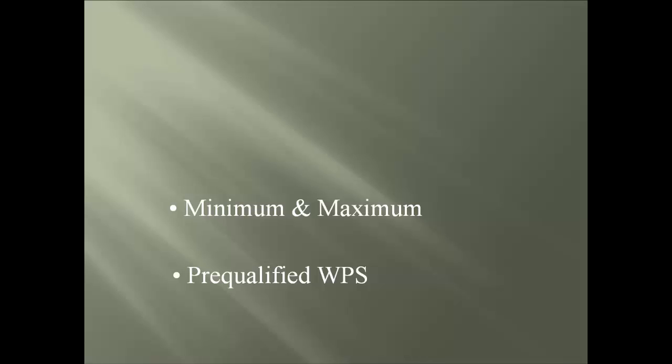Now, when the contractor does this, it's defined as exempt from a qualification test as long as the assembly is between sheet steel to sheet steel or sheet steel to a structural member equal or less than 3/16 inch in thickness. And if any deviation from the joint details approved by the AWS committee happens, this will have the proposed WPS needing engineer approval before production can begin.